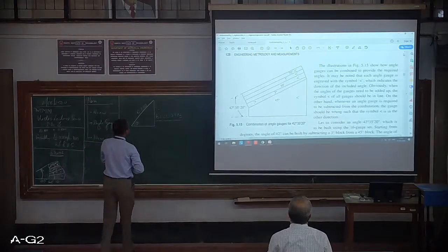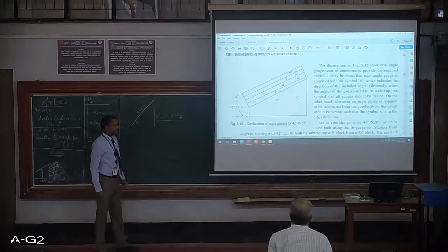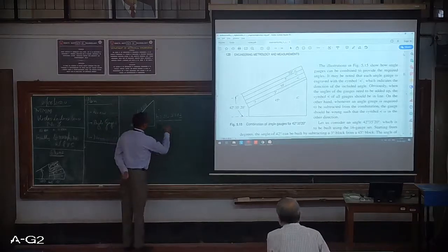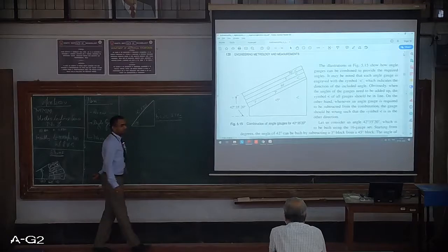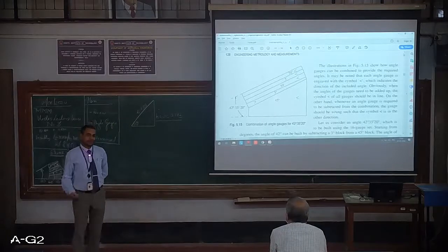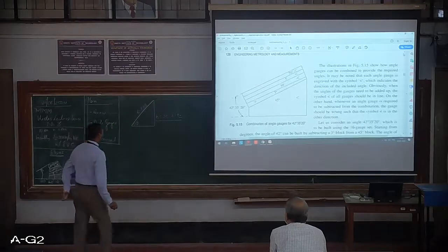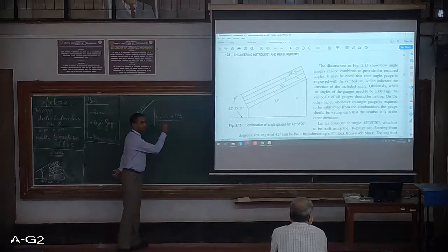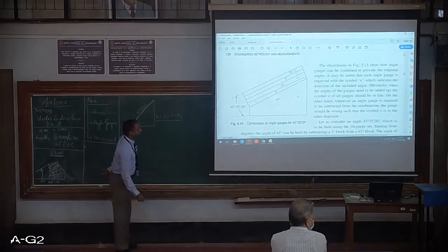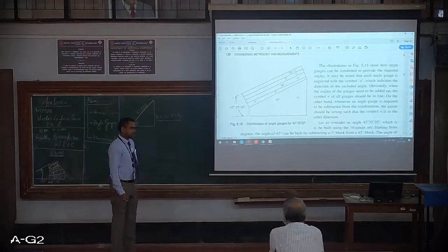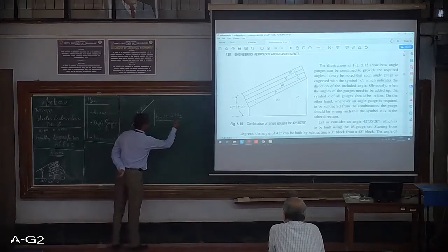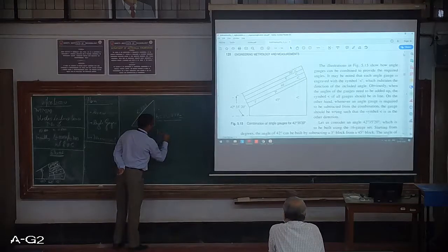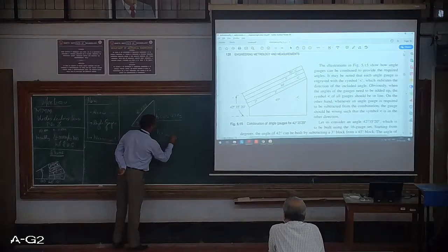As you all know, we are supposed to use slip gauges to set this particular height of 21.3782. And as you are aware, setting 21.3782 mm using slip gauges is not possible. Either you can set it to 21.3780 or 21.3785 millimeter.